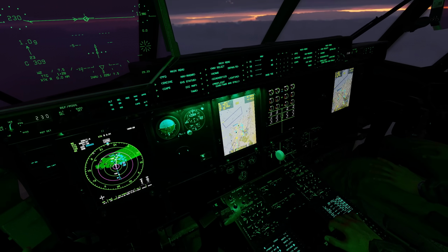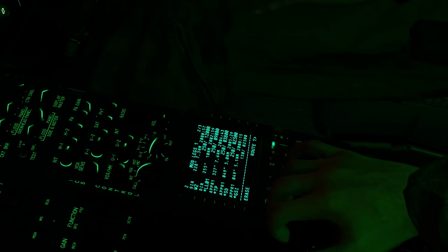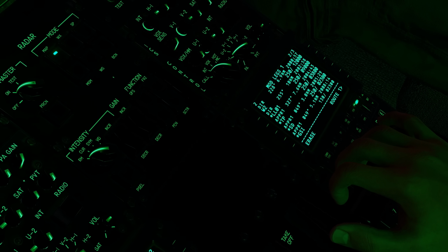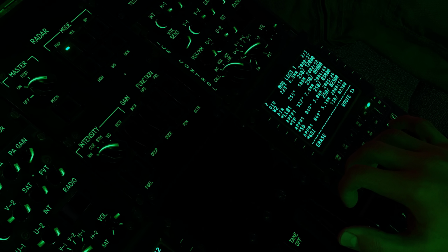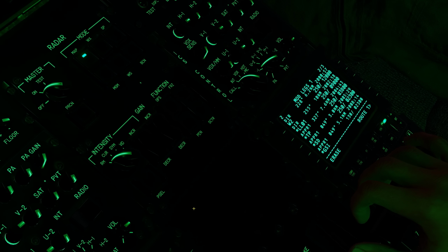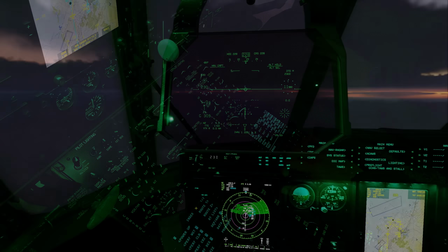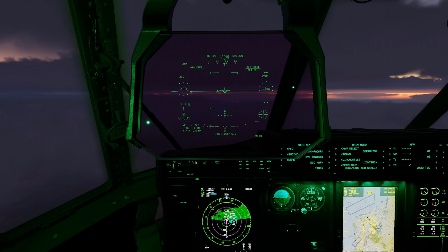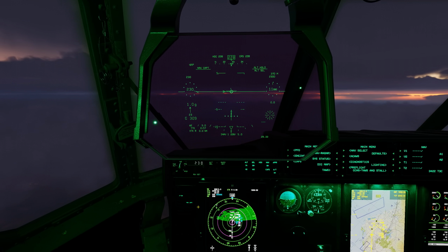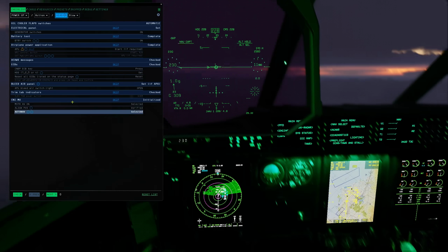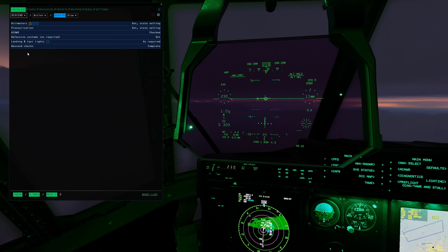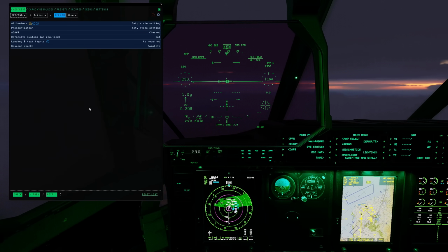Alright, for the waypoints, we're going to be 250 across the board up until GSI. Between slowdown point and GSI, we're going to slow down from 230 knots to 130. We're going to cross LL01 at 9,000, turning point to approach fix at 3,800, and slow down at 2,300. Okay, yeah, that looks good. I'm gonna go ahead and pull up the checklist for descent. And let me know when you're ready for the descent checklist.